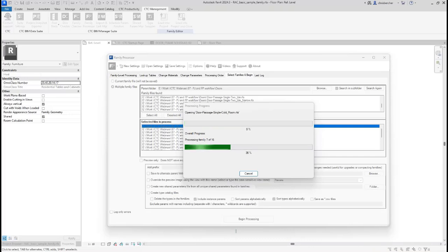If you know for a fact that your project is set to use custom parameters, or I guess I shouldn't say custom, but you had created a project specific parameter file because of the project style you're working on the customer, you can quickly export your shared parameters from the project and check it against that.